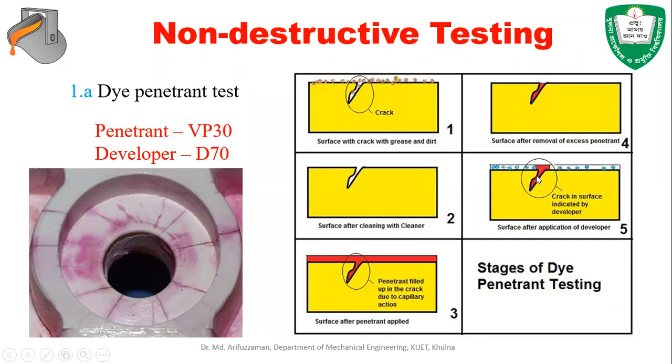Okay, and the detection of the change, you already detected through your eyes in this case. Then you interpret that when there is penetrant coming out there, that actually indicates a crack on the surface, and then you can interpret how much crack, how long the crack is, how deep the crack is. These are the detection and interpretation.